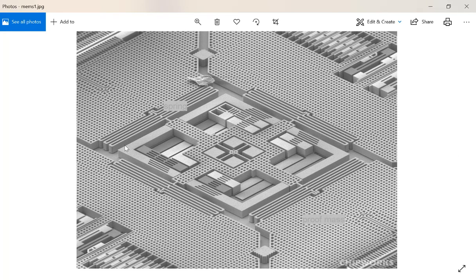And the first step is to deposit a metal material, or any other material, on a wafer, and then apply a material called photoresist, spin coat it on top of the active layer you want to use, apply a mask, and then UV expose it, and then etch out the photoresist, and then apply etchant to etch the metal layer. Eventually, you can get the feature you desire on top of the wafer.